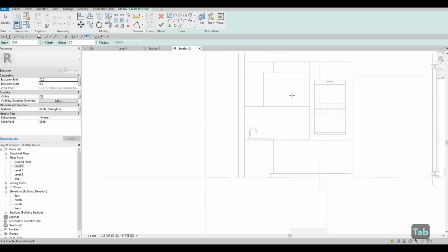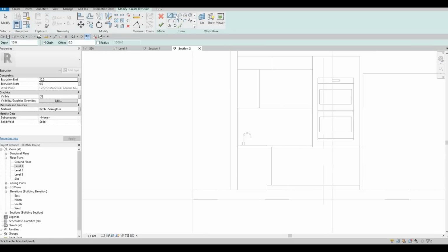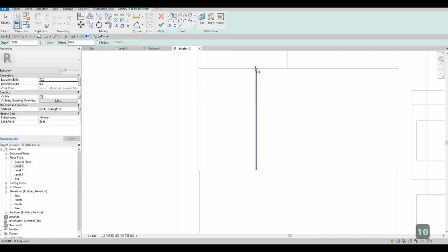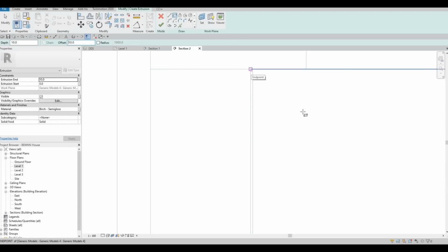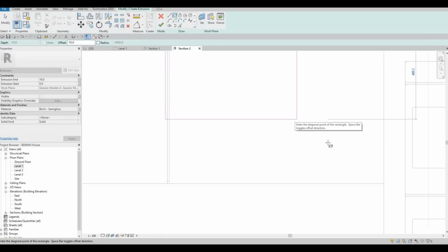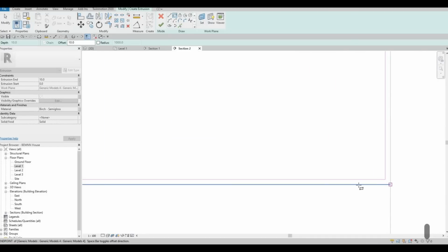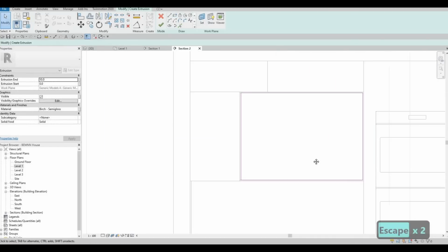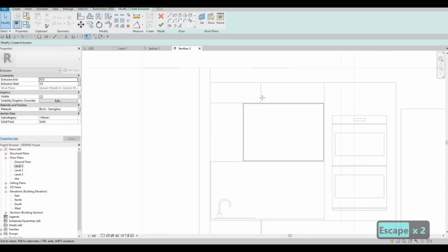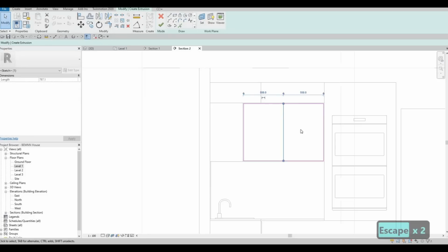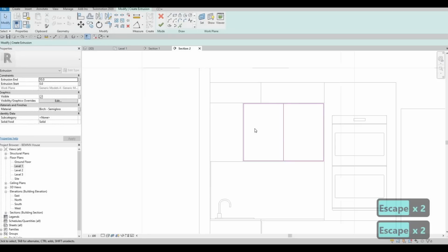And then we could just click on extrusion again and then pick this plane. So now that we click that, we can then click on the rectangle and then put 10 on the offset right here. And then let's do the corner to corner again. Space bar 4 to change the orientation going to the inside. Now this one, I believe we could just add one more. So I think that's good enough, 550, 550 each.